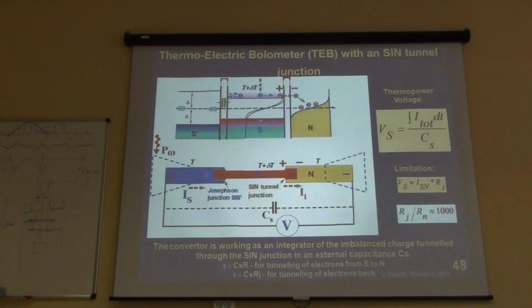So you know, Goldsmith is doing this snake, a long superconductor snake, and he is thinking about something like bolometers combined with an antenna. In this case, we should use many bolometers to fill some area, because the size of these bolometers for 15 terahertz, 20 micrometers, is 3 micrometers, quite small. Yes, we should fill some area, and then we should combine all of them, and they should wait for photons. Then one should be excited, and some photons should be registered. Not so easy, because it's a large system, and what will be the noise and combination and so on.